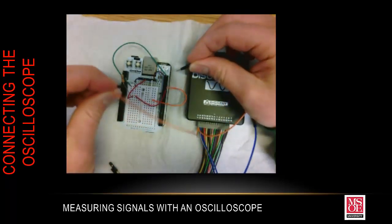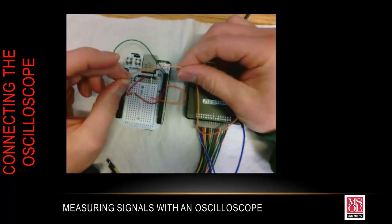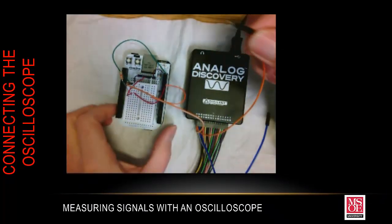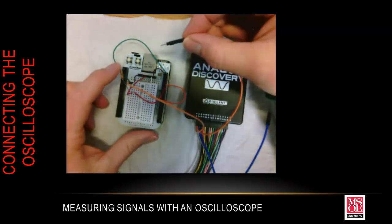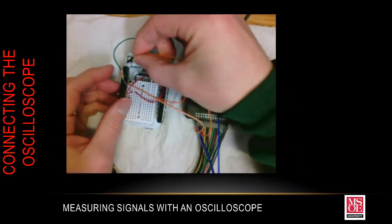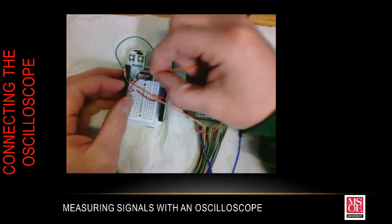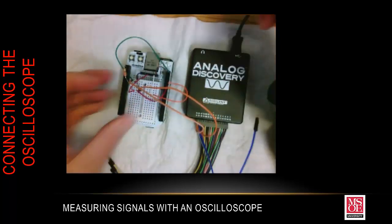So I'm going to slide this in, like so. My other connection, which does not have the white line, is the positive connection. What I want to do is connect this up to the switch. Now my switch is connected. If I look here, here is my pull-up resistor, right to this row. So here's the resistor. This is the high voltage going through here. This line then runs over to the switch. So if I put it right into that row right there, I'll be able to see the switch.